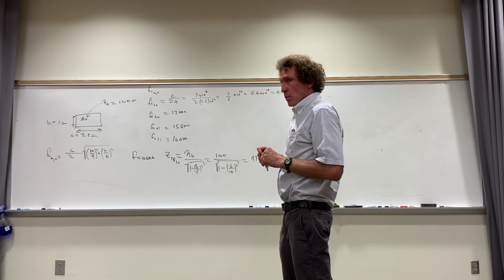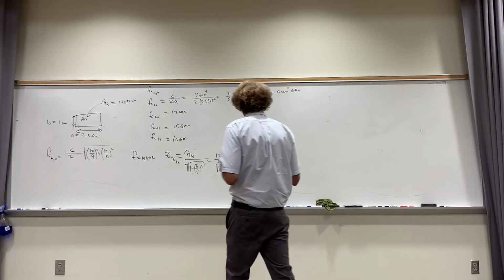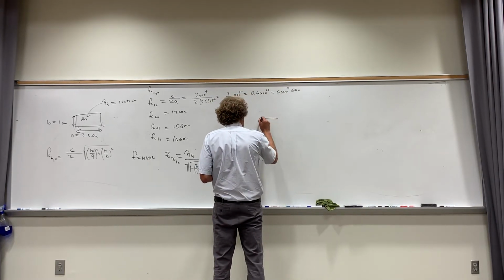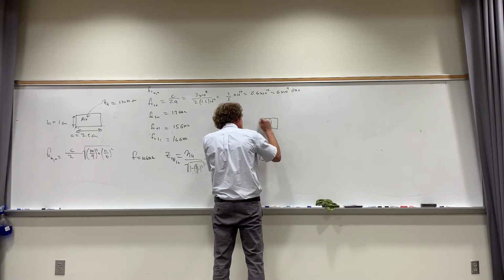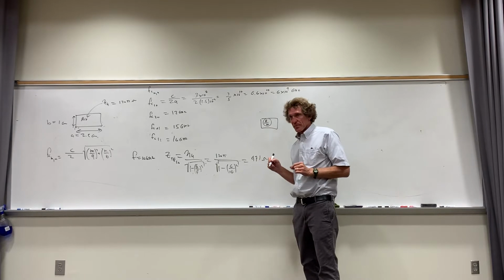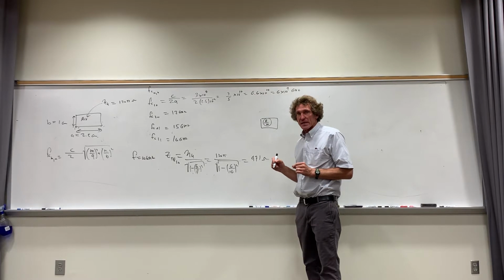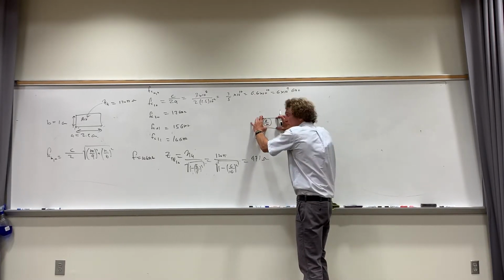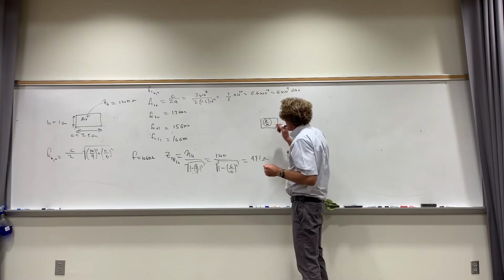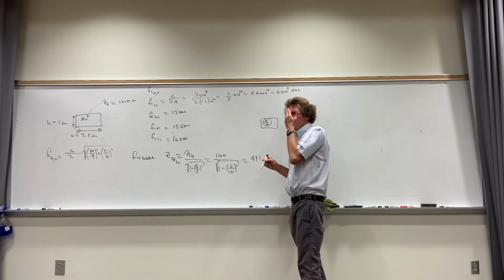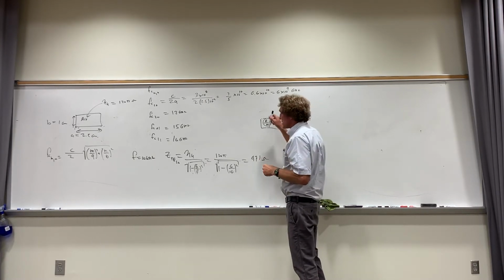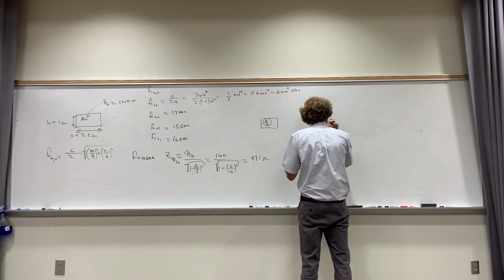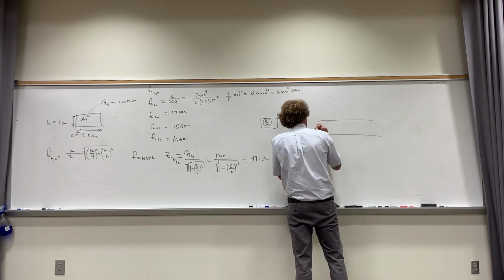Well, what does that mean? It means that if I have this piece of pipe, and I'm looking at it this way, what really is the E field to H field ratio around there is 471 ohms. Follow me? So now if I want impedance matching, think of it as a coax cable. Then I want this feeding something that is going to have a matching impedance. See, this is something you haven't really delved into yet. It's going to be a little more complicated until I go through antennas. What they really do with these things is, if you have a waveguide, let me look at the cross section of this, like so.